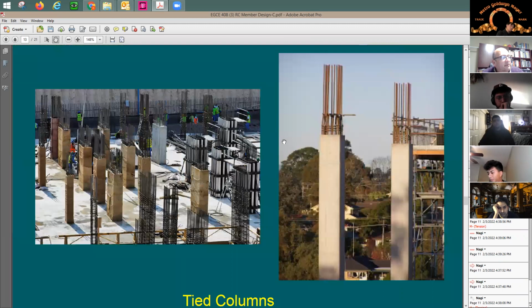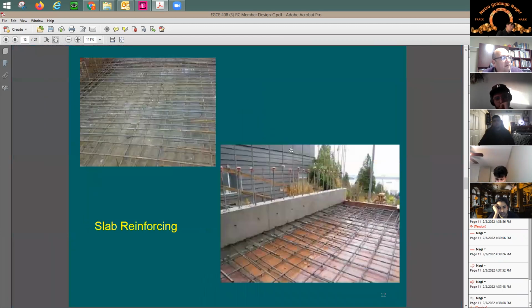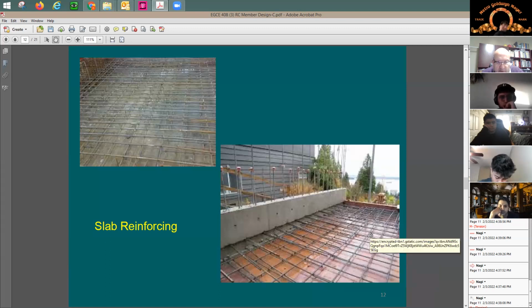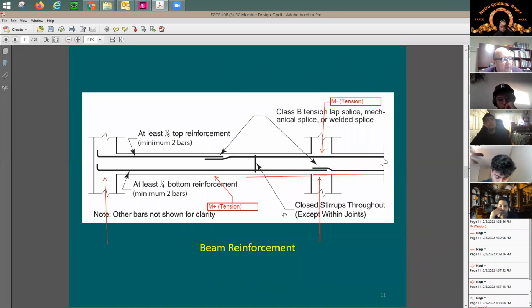Same thing with the concrete slab. They put first the formwork, it's gonna be flat. It's gonna be supported on some shoring, like steel members and sometimes aluminum members. And then they put the reinforcing on the top of the form. And then after that, they put the concrete from the top. And then they wait a few days, and after the concrete is hardened, they release the form. They take it out. Sometimes they say they strip the form. When they take the form out, you're gonna have here clean surface of the concrete slab.